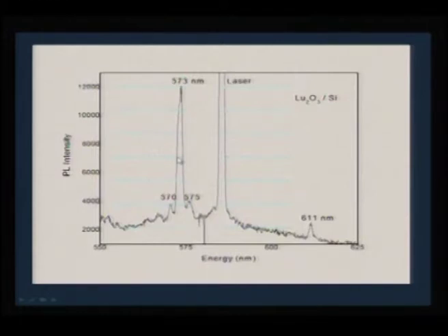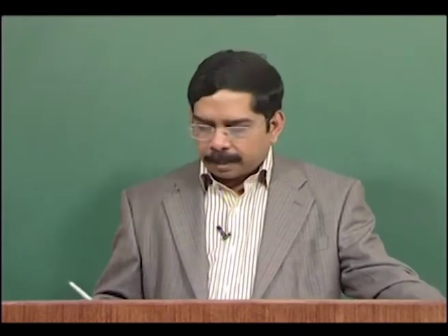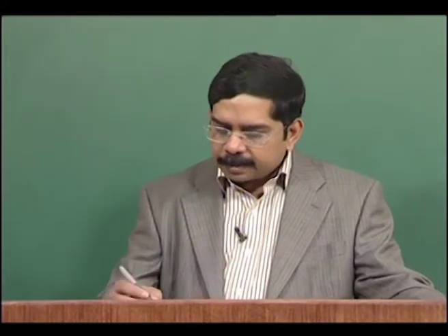Incidentally, the full width at half maximum of this emission peak is only 1.2 nanometer. So if it is showing such sharp emission, then you can see the lasing action of such emitting material. This can be made by PLD, and this is a good TEM image that tells how PLD can clearly help you in growing epitaxial films.